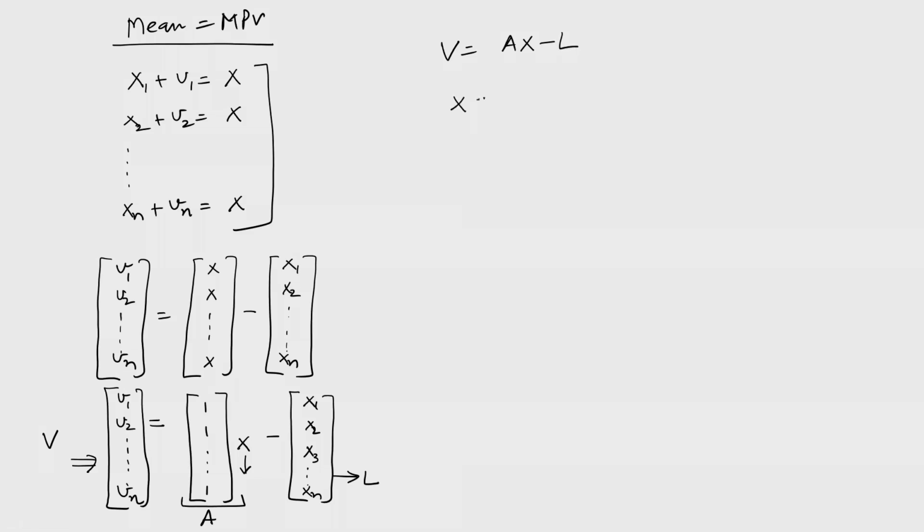So I have this form V equal to Ax minus L. I can find out x given by (AtA) inverse AtL. Okay, very simple. Now let us put the value of A and everything. It is very simple to put. At will be the transpose of A, so 1, 1, 1, 1 like this. Again the A matrix 1, 1, 1 this way.